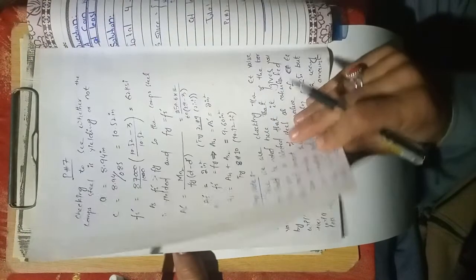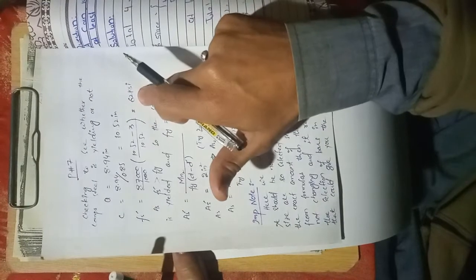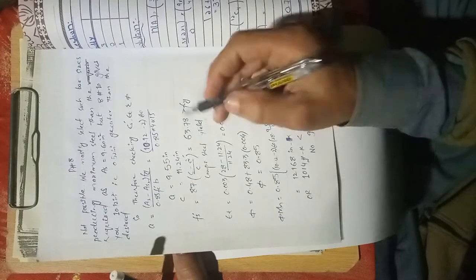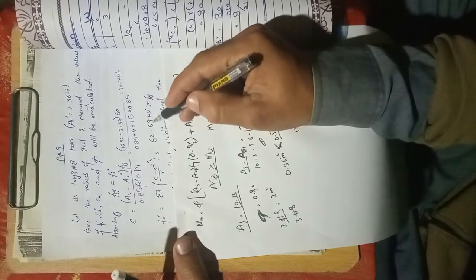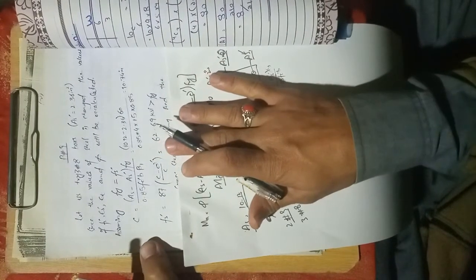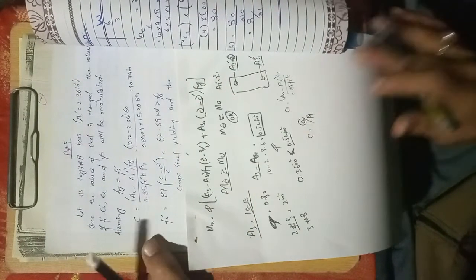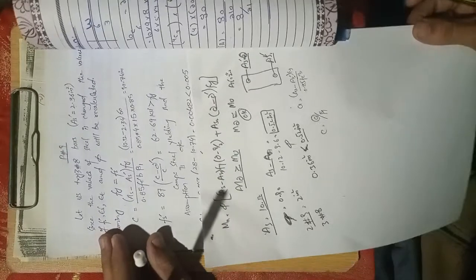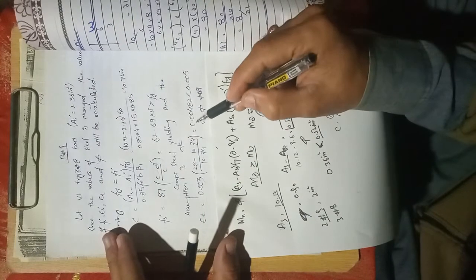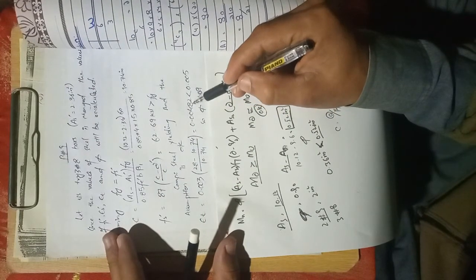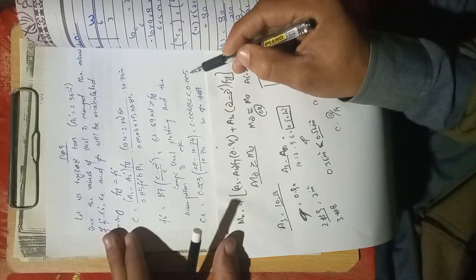In that case, if you see here, fs prime is also here 62 ksi, right, in that stage, and here it is 63.78, but here you can see it is 62.69. So still the yielding criteria is fulfilled, and compression steel is yielding. This means compression steel is yielding. We need to find out the epsilon t value, and epsilon t value is 0.00482, which is, you can say, 0.0048, very very close to 0.005.